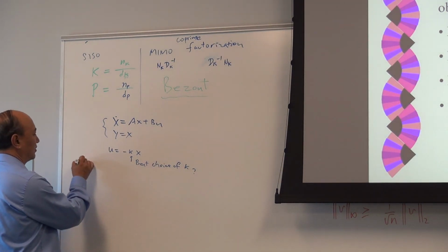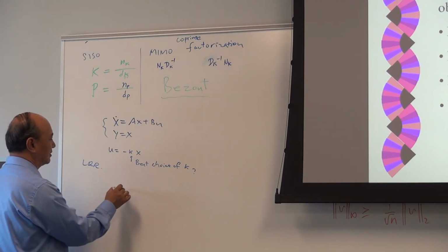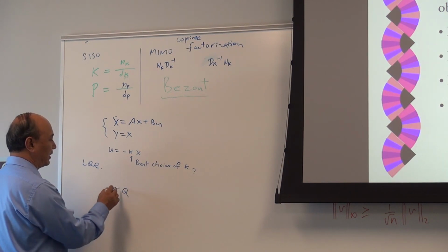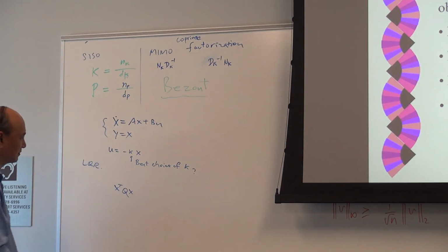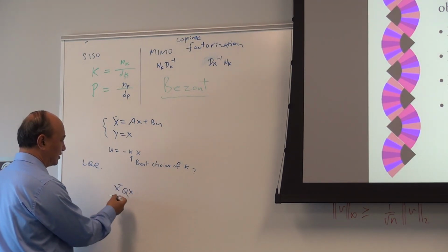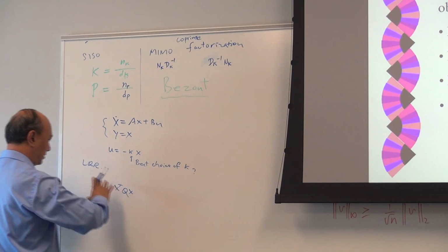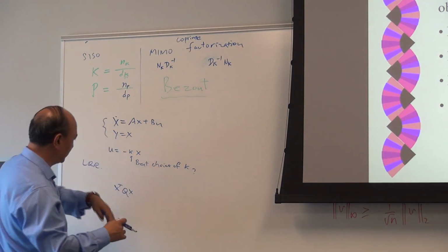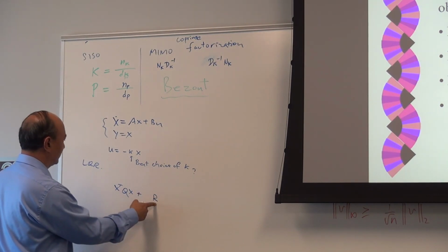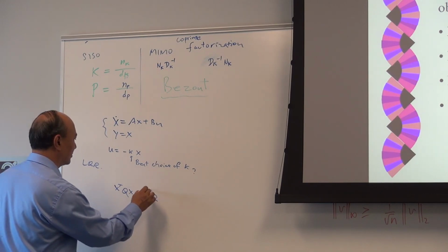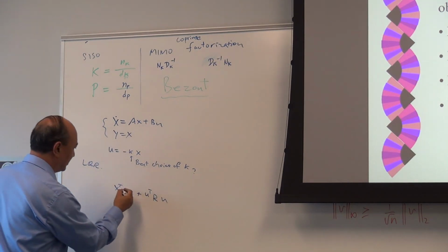So here is something called LQR. I have a matrix Q that penalizes my X transpose X. This is a quadratic. Q is semi-positive definite, so this is a scalar cost. And I have another matrix R that is positive definite, and you have U transpose U. This is the MIMO case, vectors, and all of these are functions of t.